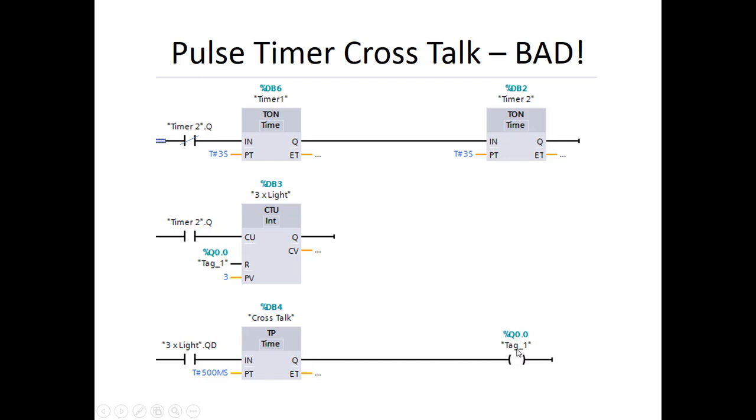You kind of lose track of your outputs. I like to have a bit here and then have another rung with a bit turning on the output.